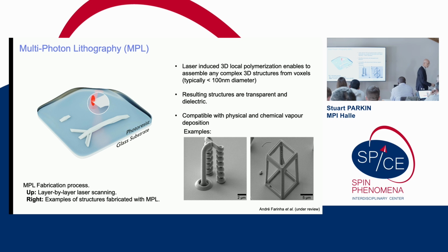50 nanometers wide. And then he can, by moving the laser beam around, using, as we heard this morning, either piezo stages or mechanical stages for the larger structures, build complex structures in 3 dimensions, as shown here. These are just simple examples. The surface roughness, in our case, I asked that question this morning, is about 0.3 nanometers. So these are pretty smooth structures, so it's very, very nice. Of course, it depends on a lot of details.